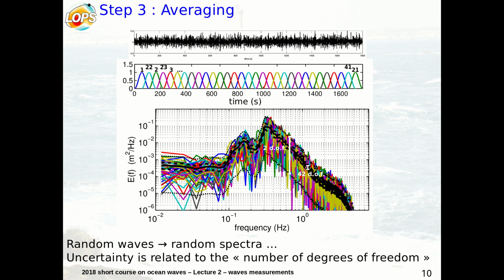If you have longer wave periods, you should typically do a longer record. If you have very long swells, because you have fewer waves, the statistics are not so good, so you may want to go longer. But on average, people consider that a good measurement is 20 minutes. When I compare to the model, I usually do 1 hour averages and make sure I have continuous data for 1 hour. And then it depends.